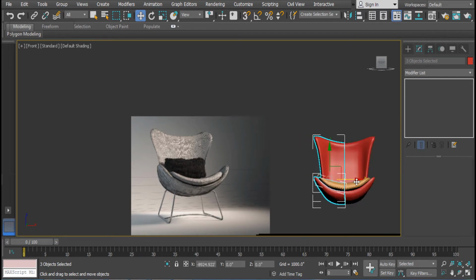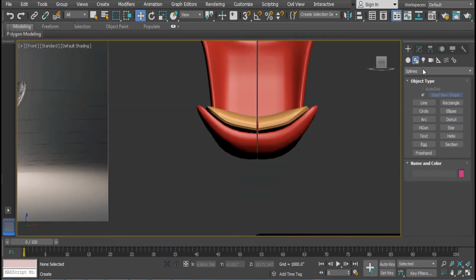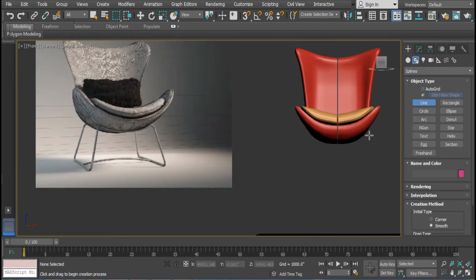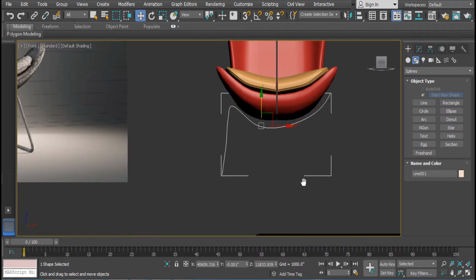In curves, you can duplicate the curve, you can attach or detach the curves, or you can weld the curve. Also, you can modify the weld. For example, in curves, the corner means you will find the sharper edge. If you need a smoother or curve kind of shape, you need to modify the corner into a bezier, so that you will get a better result. So in this tutorial.